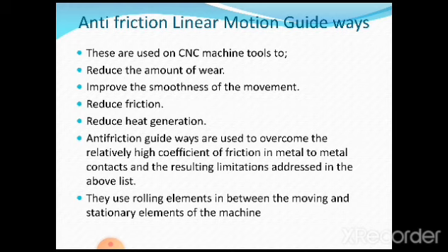So now we shall have an understanding about the linear bearing with balls. These are considered as the different types of LM guideways we are discussing now. These are called linear bearings with balls because a linear ball bush uses recirculating balls within a bush type of bearing.